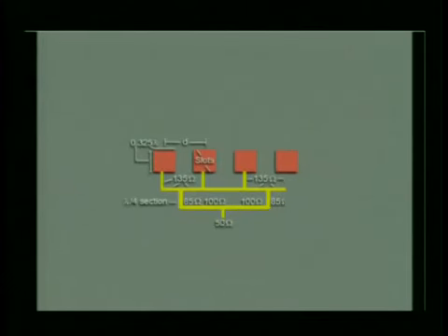Look into this animation. This is a 4 slot antenna array. It has a feed network. Look into the feed network, how it is going. Start, your 50 ohm is at the bottom, because that 50 ohm will be connected to the source.